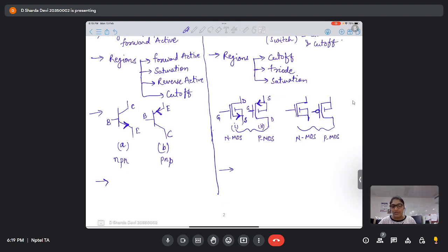Let's say input voltage versus output current if we are plotting, how will that curve look for a BJT? Exponential curve. Yes, exponential. It's dependent exponentially on VBE, meaning input voltage. Exponential IV for BJT, right?